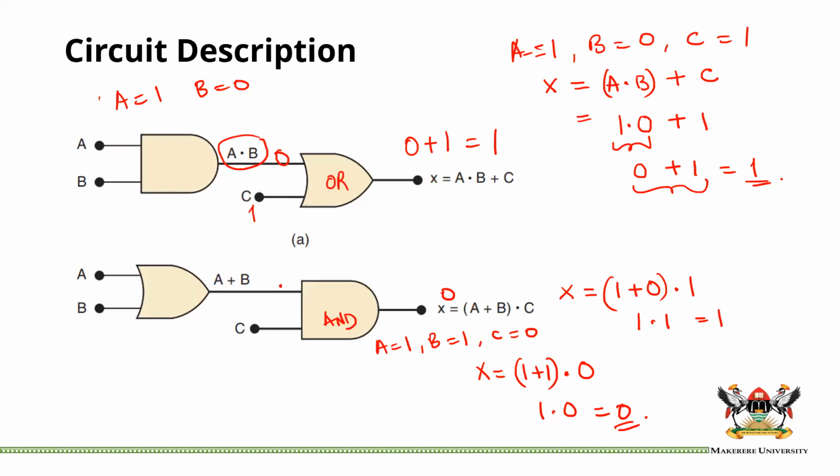But generally with control gates, it's better to use the AND. Okay, because the idea is that you want to pass one of the inputs to the output or not. And the AND does it very well. Because you can see for it, as long as B is a 0, A will never go to the output because it will always be a 0. But we can also use other types of gates, as we are going to see later on. For now, you can take it as an AND gate, but I've really just brought it way ahead of its time.